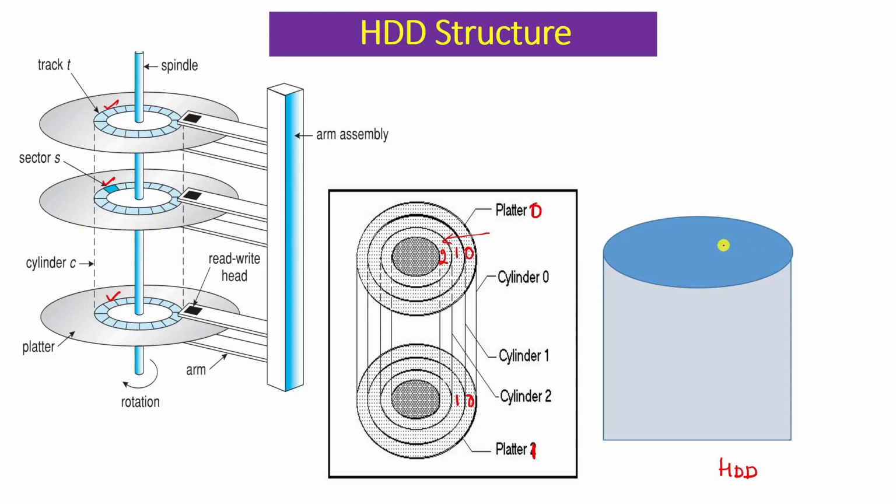You know that a hard disk has a controller. What is the function of this controller? The controller takes requests from external sources. Let's say a request from the operating system comes; it goes to this circuit board, the controller. Each input and output device has a controller associated with it, for example the keyboard has a keyboard controller and the printer has its own controller. It is simple circuitry which understands the request. When a read request comes, it is forwarded to the controller, and the controller instructs the arm assembly and the motor to get the data from the desired sector.